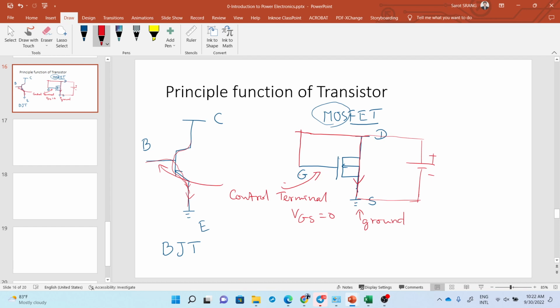That's why we call it an electronic switch. If you want to switch on or off, you need to send a signal through the gate. And the signal that you need to send can come from the battery itself or from a microcontroller, for example something that has a chip. Then you can program it to send a signal from its terminal, let's say like this.